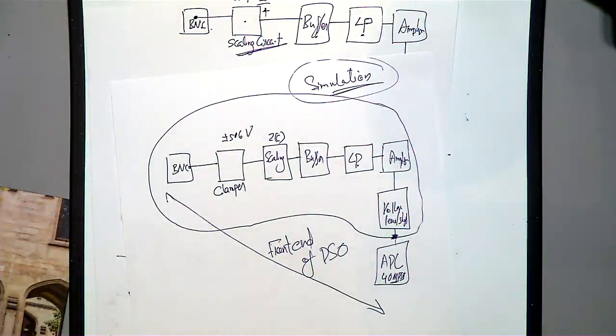How to design: you already saw some circuits, and now I will show you an example. Can we combine the low pass filter and amplifier together? Because we are going to use an op-amp for the second order filter, so we can use gain and use that as an amplifier. The low pass filter we will be designing using an op-amp. With feedback, can we use that as an amplifier as well, or should we use a separate amplifier? It's up to you. You can maybe design them together. Amplifier and buffer, sometimes you can change. These are the general ways we design a system, but based on the requirements, people implement in different ways.